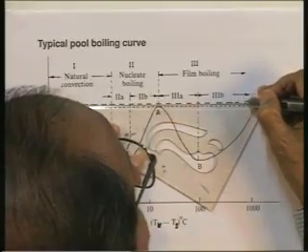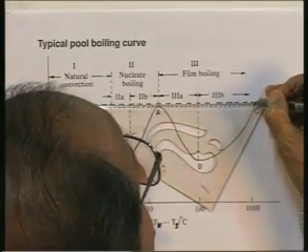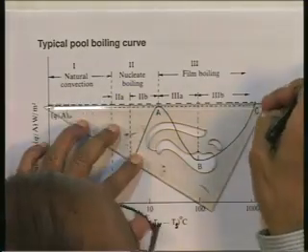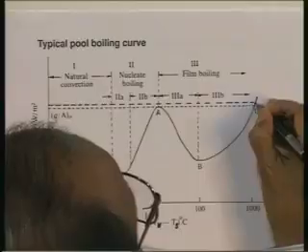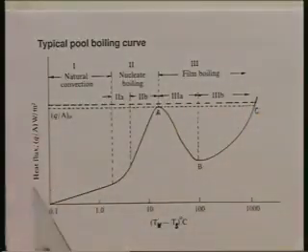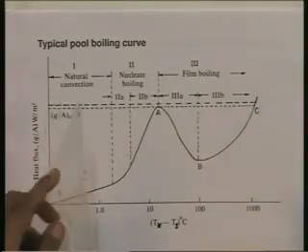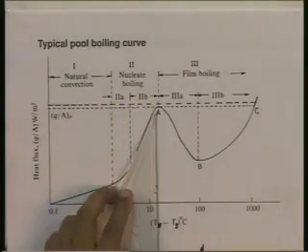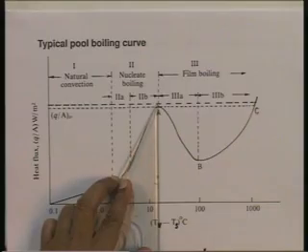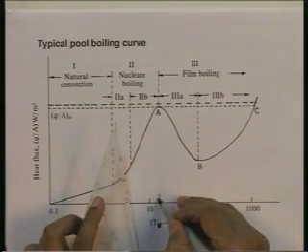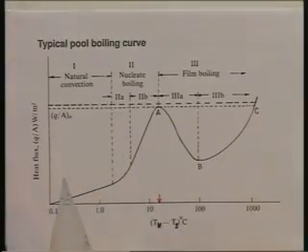Now, notice the value of T w minus T s now suddenly will go up. Earlier, if I was at the critical heat flux, that is at this point, the value of T w minus T s was given here, with q by A critical.